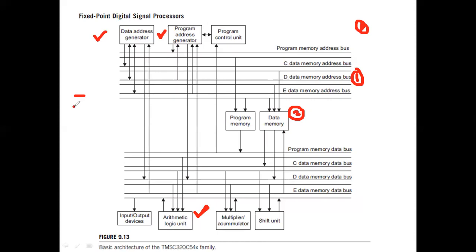Now suppose you have to run through these instructions. Say there are some 5 instructions and say there is a jump, jump to a previous label. When you have to do this, you have to keep track of where exactly to jump, or if there is a subroutine call, right? You remember the procedures where you have to go to a different set of program somewhere in the memory. So generating the program address for a new location becomes very important. And in all these cases, usually in a general purpose processor, your normal ALU would be used. Here a separate program address generator is there.